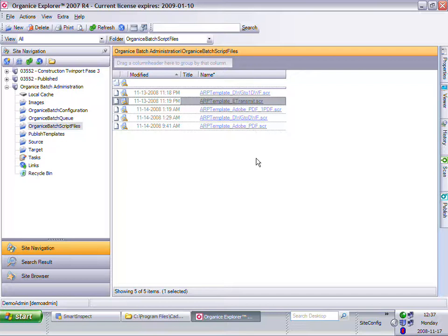It's a standard AutoCAD e-transmit, gathering all the information that a drawing depends on, like the fonts, the different AutoCAD reference files, the image files, the font mapping file, etc. So you're sure that if you send that e-transmit, somebody can open the drawing the same way that you are opening it at your company.